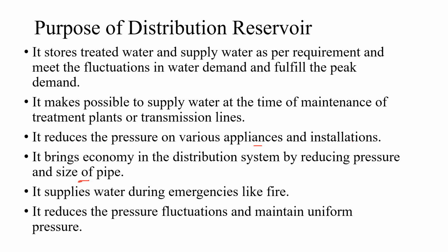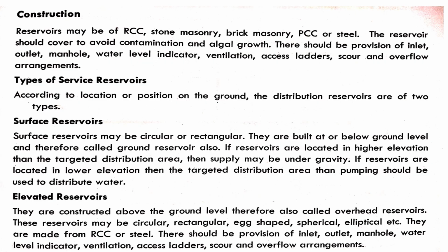It supplies water during emergencies like fire and during breakdowns, right? It reduces the pressure fluctuations and maintains uniform pressure. Distribution chambers usually facilitate us for these types of points. Reservoirs may be RCC, stone masonry, brick masonry, PCC or steel. The reservoir should be covered to avoid contamination and algal growth. It should not be contaminated as well.